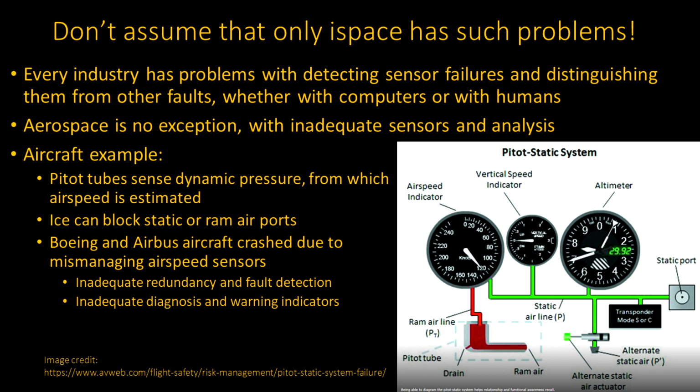Those kind of problems aren't always thought through, and they don't always put redundant sensors in. And that's killed people, literally, both from Boeing and Airbus customers. I know it happened in the case of an Airbus craft. It was an Air France flight out of Brazil, and it crashed pretty much because of icing and failure to recognize what happened. They didn't know what altitude they were at. And actually, Boeing has had exactly the same problems. So it's even a well-known problem in aerospace, and still, in the case of Boeing recently, they didn't want to actually put in the extra sensors or even provide decent warnings and training to people about it. So it's really pretty common. They don't have the redundancy built in, and they don't have the logic to exploit redundancy if they have it. It's one or the other.